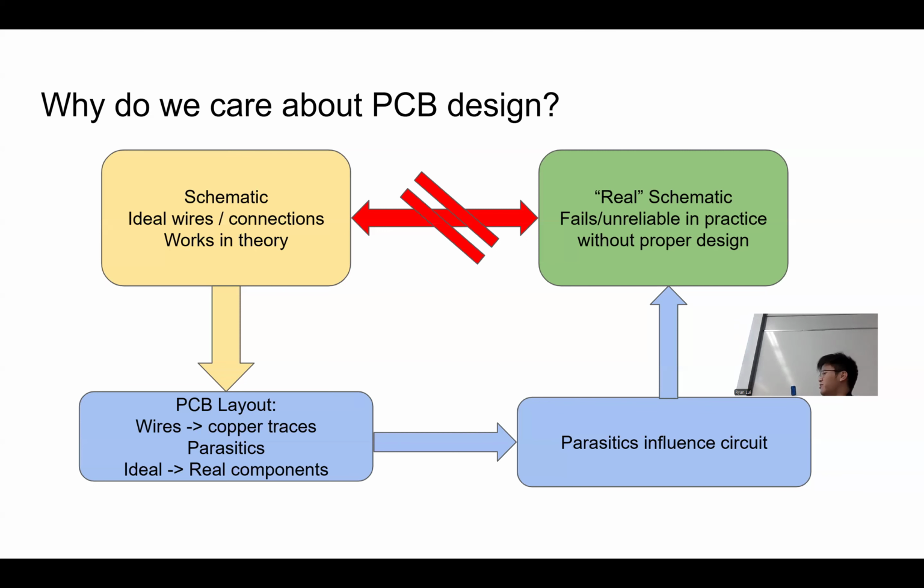And your components aren't ideal either. Your capacitors can get devalued if you put too much voltage on them or if you have them too hot. You have to deal with real components, and it sucks. So we care about PCB design and how we lay out everything because we want to minimize these parasitics.